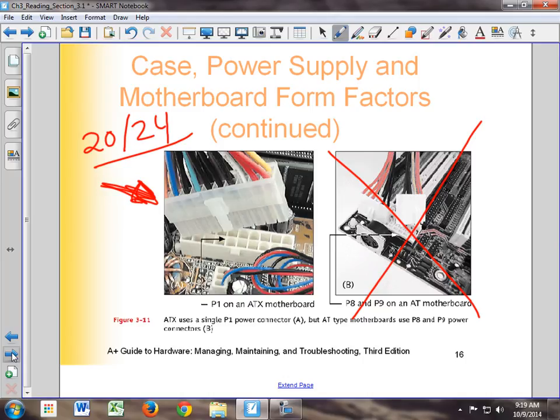So it plugs in there on the motherboard, and it provides the majority, not all, of the power on the motherboard. Okay? I also have another plug over here that was added when we went to Pentium 4s because the processor requires so much more power. If I don't have this one plugged in, it goes right here, it will not start. It will act like it's going to start, and then it will fail the CPU check on the POST.